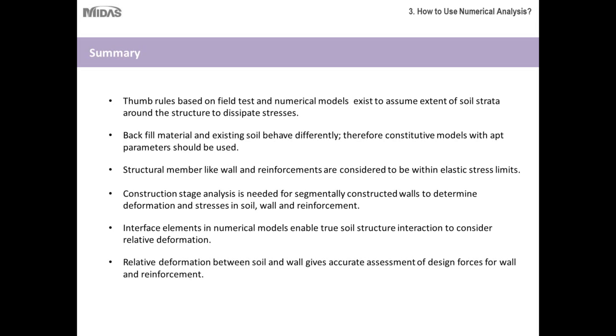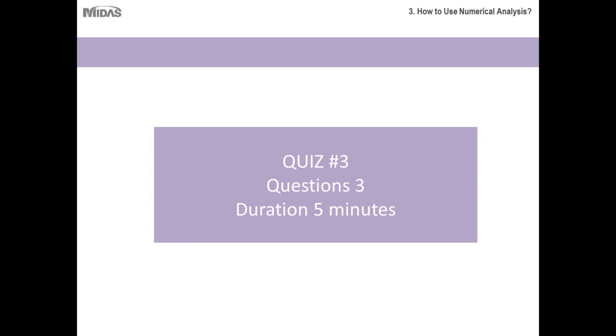The interface elements in numerical models enable true soil structure interaction to consider relative deformation. And relative deformation between soil and wall gives an accurate assessment of design forces for wall and reinforcement. And finally, interface properties are dependent on soil type and inputs can be obtained from the field test.